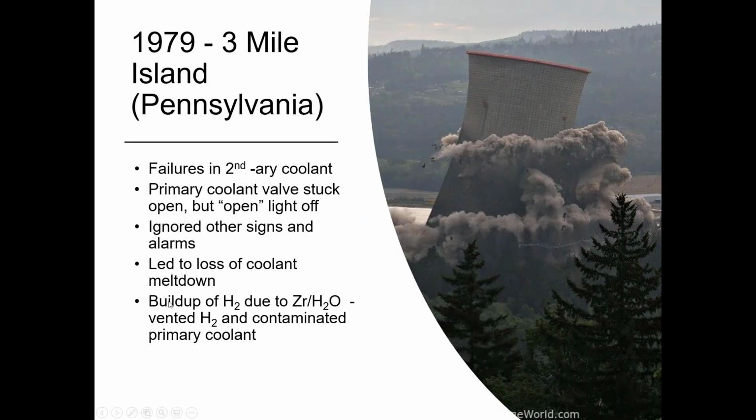So while that happened, there was also a buildup of hydrogen due to a side reaction that just usually takes place in a containment structure. And so what the operators decided to do was they decided to vent that primary containment system in order to get rid of the hydrogen gas, because if hydrogen is mixed with very, very hot temperatures, well, eventually that hydrogen will explode, okay?